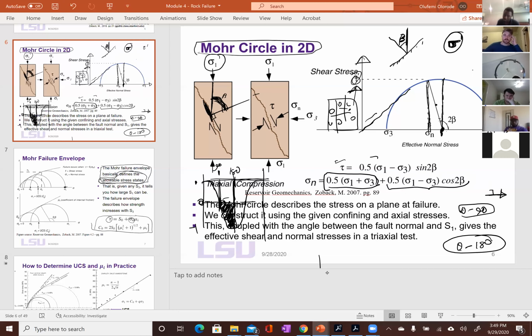So it's not always negative. If your angle is between 0 and 45, say 45 degrees in particular, you'll be here. Right? So sigma n is not to the left of this radius, it's to the right. So this is your sigma n. So how do you get the correct value? The first component took you to this point, right? Well, you now have to add this value. So this will be positive in that case. So the equation takes care of all angles, all beta values going from 0 to 90.